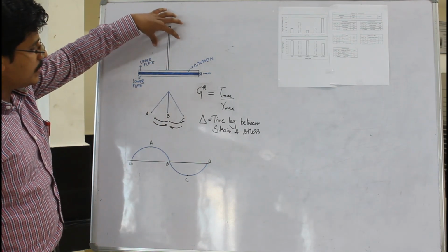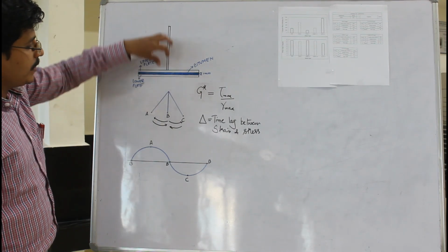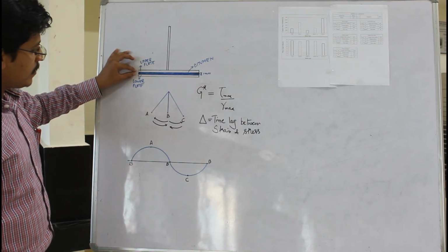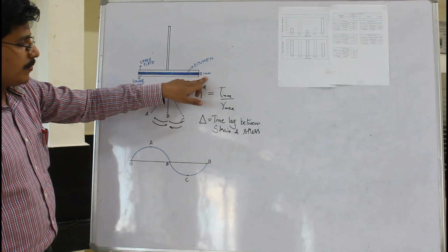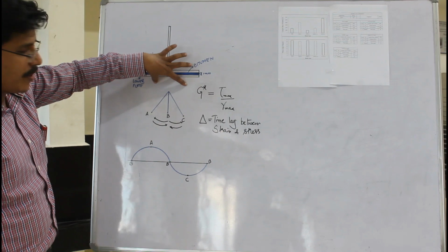This is a plate which is fixed to the motor. This is the bottom plate, which is fixed. This one is movable and this one is fixed. In this, we placed a bitumen with a gap of 1 mm. The thickness of the bitumen was 1 mm and the diameter was 25 mm.